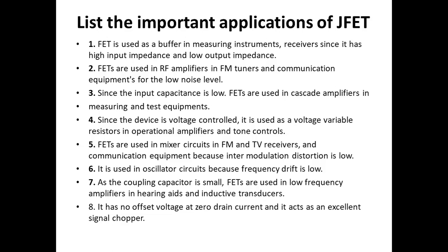And the second application is FETs are used in RF amplifiers in FM tuners and communication equipment for the low noise level. So field effect transistors are used in RF amplifiers in FM, frequency modulation, tuners and communication equipment. And since the input capacitance is low, FETs are used in cascade amplifiers in measuring and testing equipment. And these devices are voltage control devices used as a voltage variable resistor in operational amplifiers and tone controllers. FETs are used in mixer circuits in FM and TV receivers.